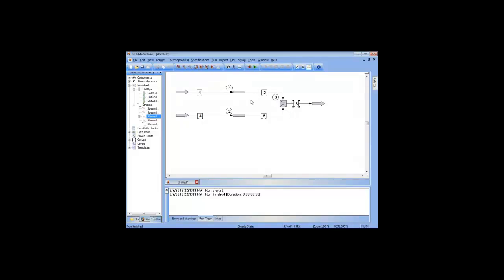In reality, this does not happen. If you've got two pipe flows combining, they will have the same pressure in both of these two spots coming into this joint. They will balance pressure drop across both lines in order to do so. In order to do that, something has to change from how we have it. We have not specified something that is actual reality. If we had it set up like it was, because this pressure is higher than this flow, you would actually see some of this flow going into this branch.